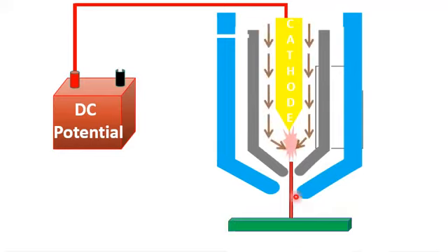Now, as I have previously discussed, the temperature of the stream of the plasma is in thousands of degrees centigrade. So basically you can melt refractory metals, you can melt any type of metal from which the cathode material is made. This makes the cathodic arc deposition process very diverse because of this plasma arc igniter.